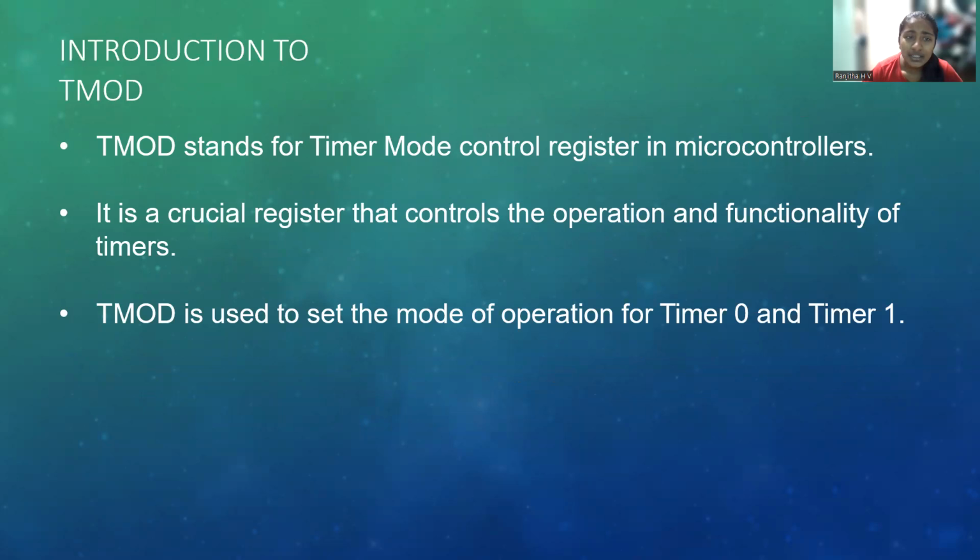Introduction to TMOD. TMOD stands for Timer Mode control register in a microcontroller. It is a crucial register that controls the operation and functionality of the timers. TMOD is used to set the mode of operation for Timer 0 and Timer 1.